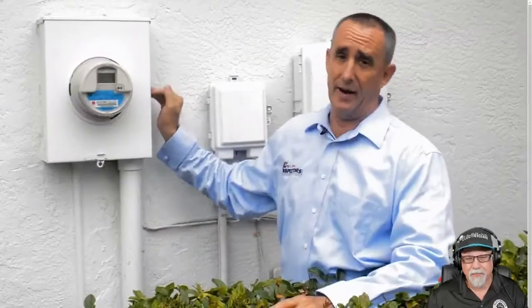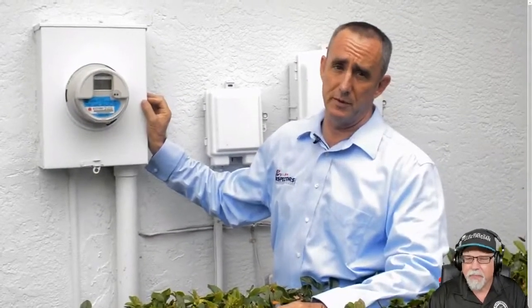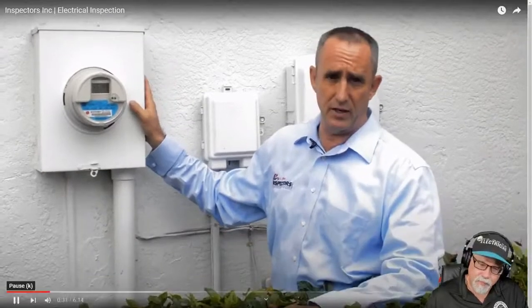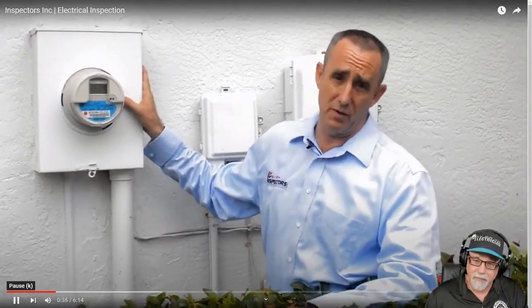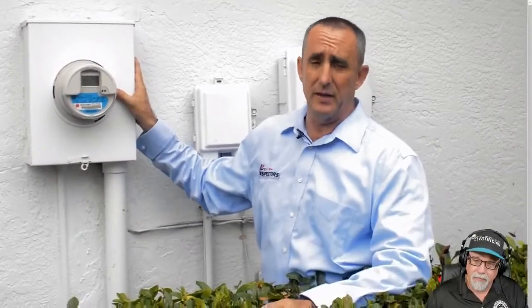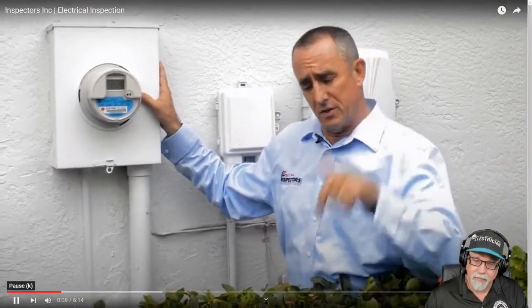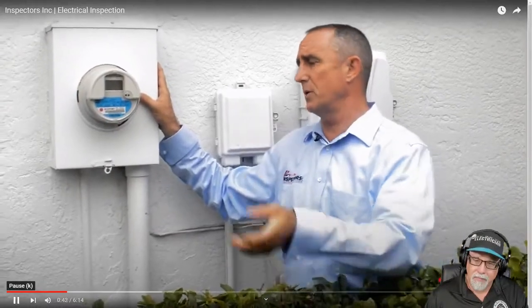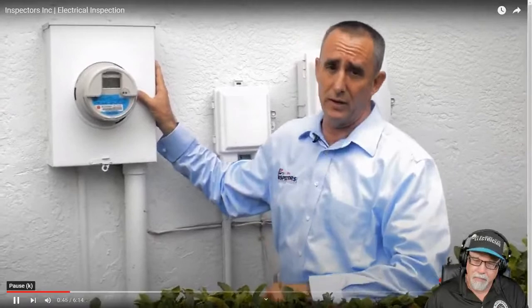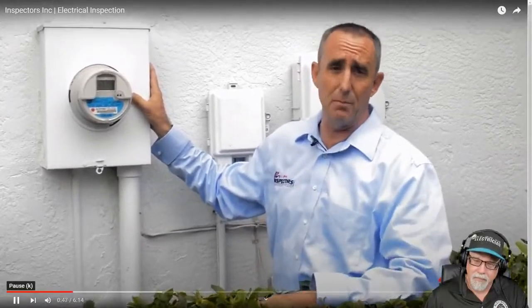The meter. After the meter, it is the homeowner's responsibility. So these are the components that we're checking, and it's the ones right after the meter. The most important one is the grounding rod or grounding system. They can either use a ground rod, which is into the ground and connected to the electrical system's grounding system, or they can connect it to a water line, assuming that the pipes in the house are metal.